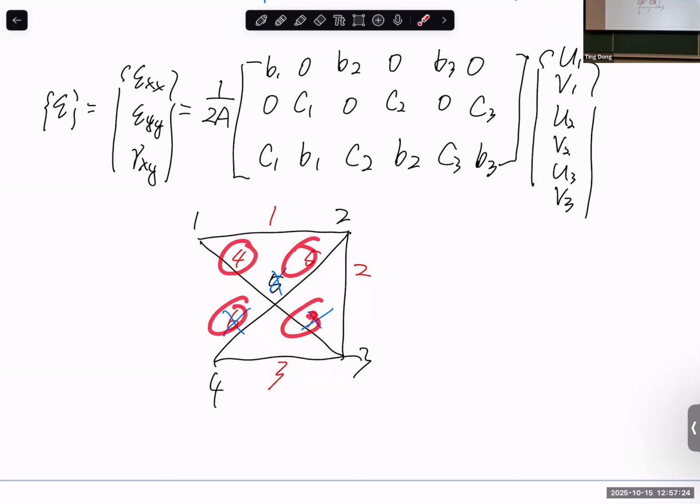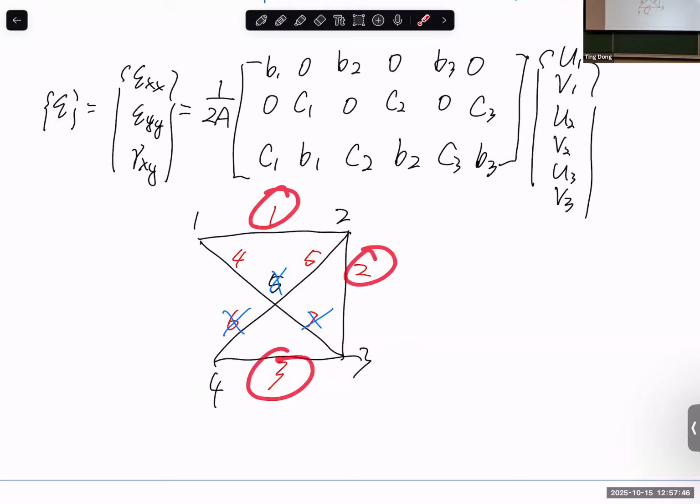And then in the graphic interface, you probably define, let's say, the cross section for this one, and you have the cross section definition for element set 1. And for these 2, you have the cross section definition for element set 2. And now, since we remove these 2, you also need to change the element set definition. So basically now, again, this becomes one set, and this becomes one set, and you don't have 6 and 7.